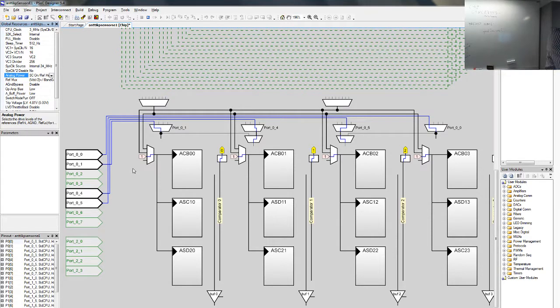So, yes. What we have here is the pin out. Okay, there on the left corner, that's one place to start defining pins, how they are connected to the next point, and if they are outputs, what kind of drive they have. Each of those pins may have 8 different driving modes.